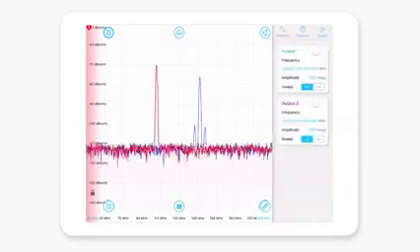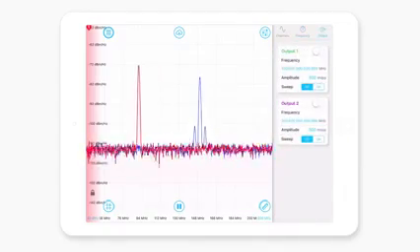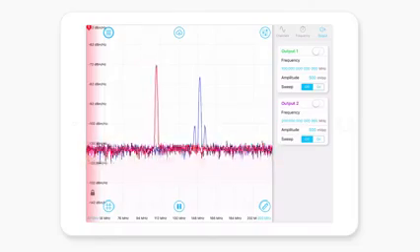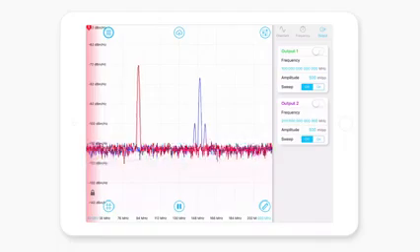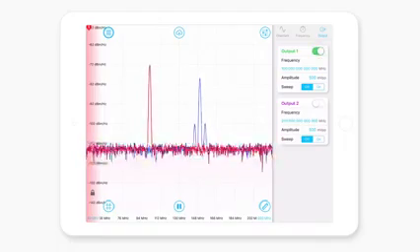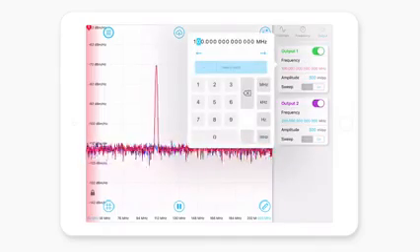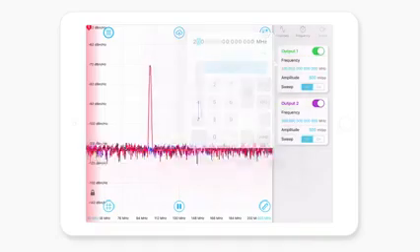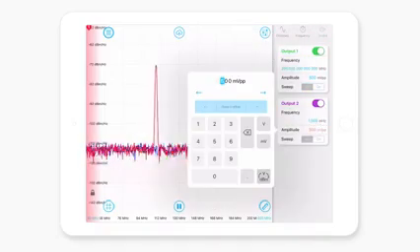All right, the final one is also a really neat feature of MokuLab's spectrum analyzer. We have this ability to synthesize waveforms at the same time that we're measuring them. So at the same time that I'm measuring signals on the inputs, I can generate different tones. I could generate one at anywhere from basically DC up to 250 megahertz. And I'll make this one 1 millihertz. I can set the amplitude.